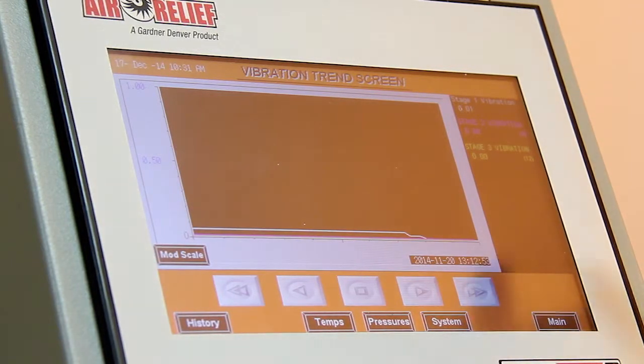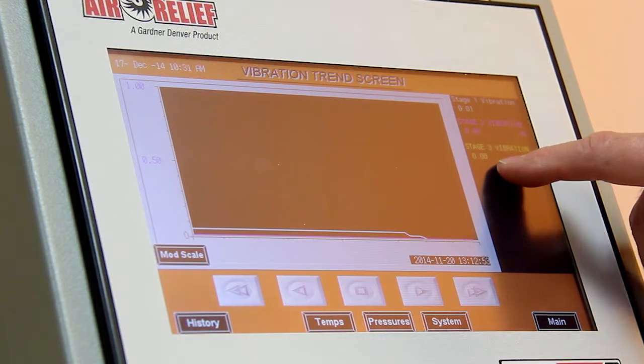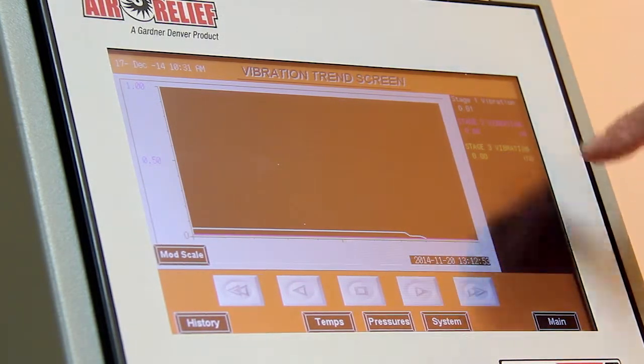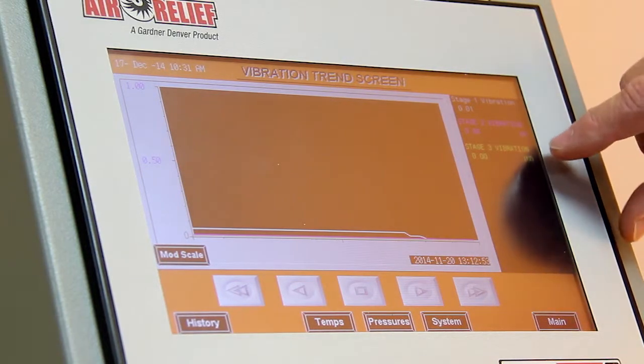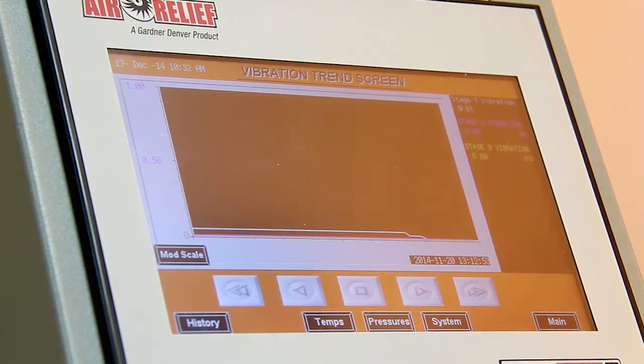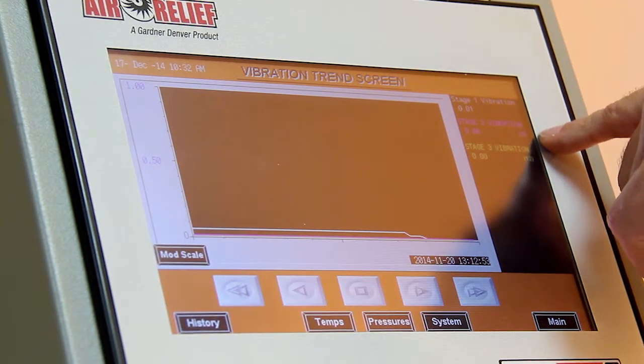Now remember, I had it set up as a 2-stage machine earlier, and now I've set and turned on the stage 3. Okay? And the nice thing about this display here, if you'll look, I've got these little labels that are showing up here, and that allows you to understand what analog input you're using that sensor on. For example, in this situation, we would bring in stage 2 vibration on analog input number 9.